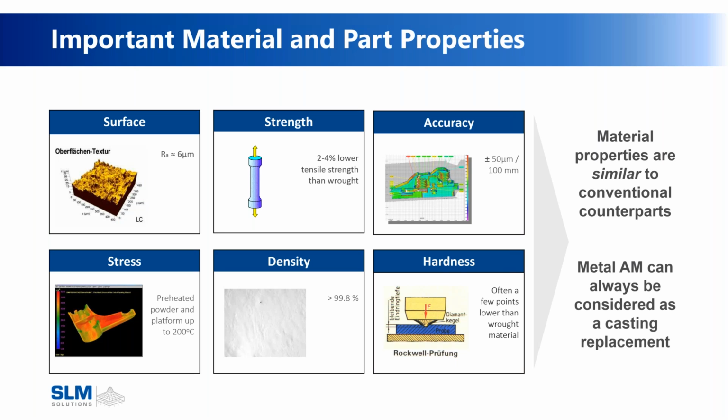Our material strength, we do a lot of testing material strength for X, Y, and Z, because metal additive is not like subtractive, where you can take an ingot and understand the exact mechanical values of that ingot, and then whatever shape you make it into will have the same mechanical values. As we're printing, the mechanical values can change in X, Y, Z, and then based on heat input, there's so much more that goes into metal additive that we really need to understand these values pretty deeply.